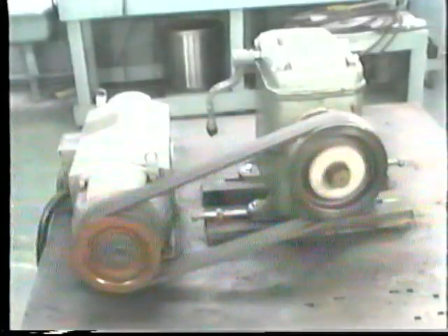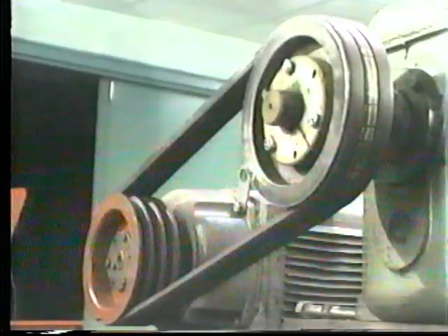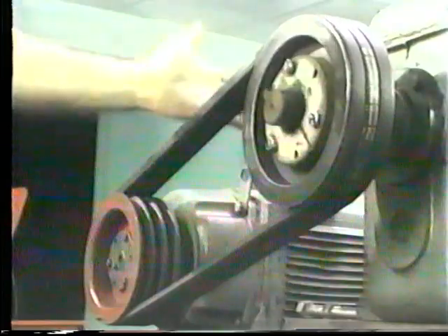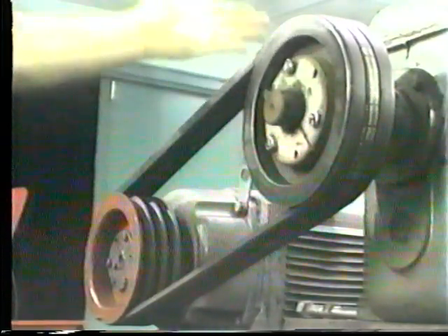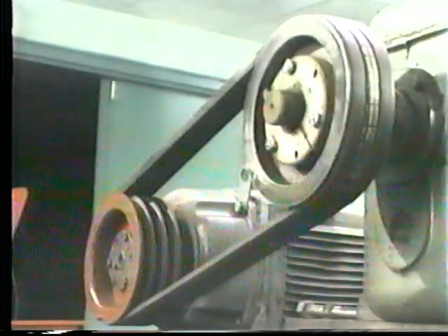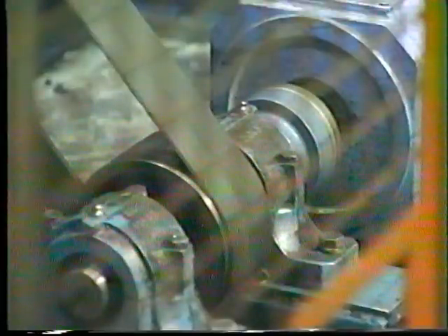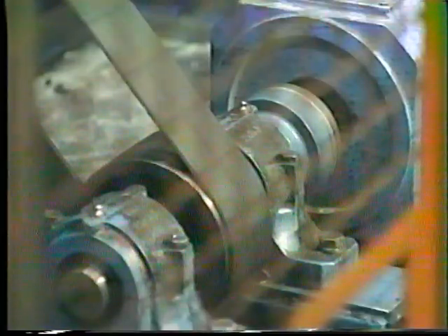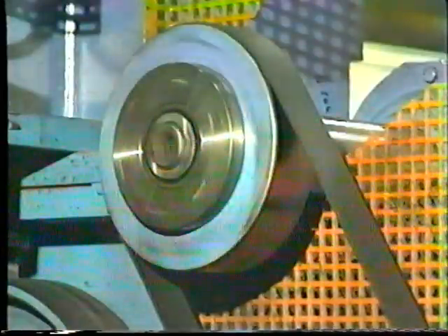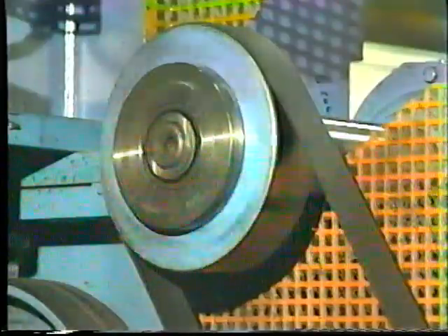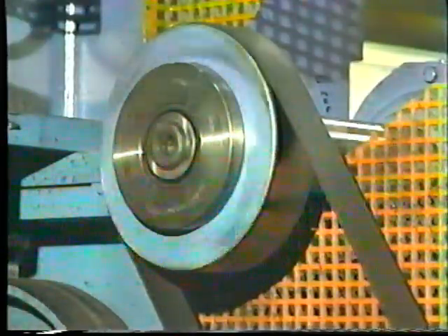Both these types of belts rely on friction to transmit power from one pulley to another. To create that friction, the tension on the belt must be carefully adjusted and maintained. A belt without enough tension cannot transmit power from the driver unit to the driven unit efficiently because it cannot grip the pulley surfaces well enough to prevent slipping. These types of belts operate well over short or long center distances, and they also cushion motors, shafts, and other components against the effects of load changes.